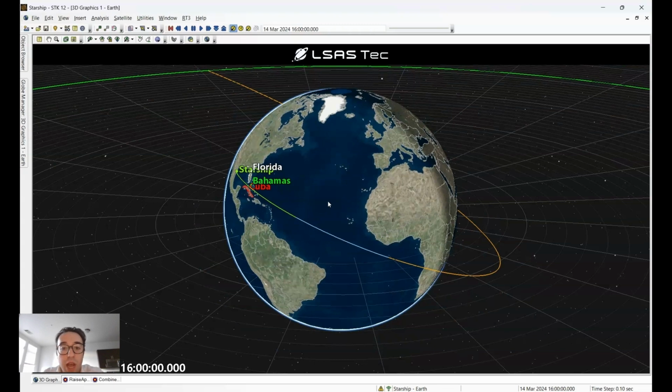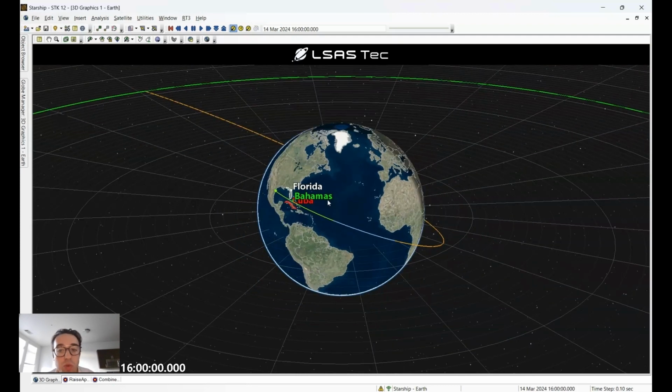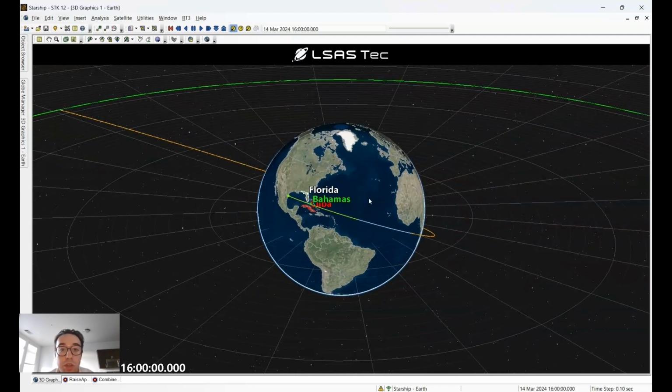And we managed to show that Analyzer can allow us to find an optimum value for our design variable. In this case, the downrange distance was 5,000 kilometers, and our azimuth was 92.3125 degrees.